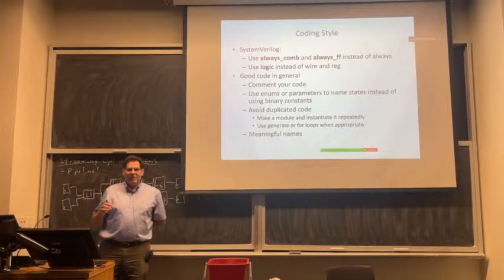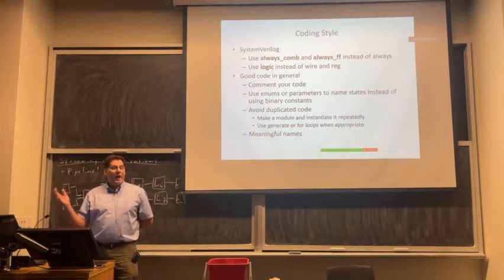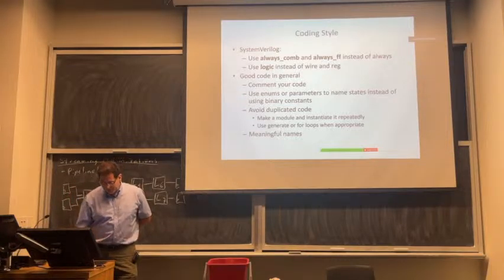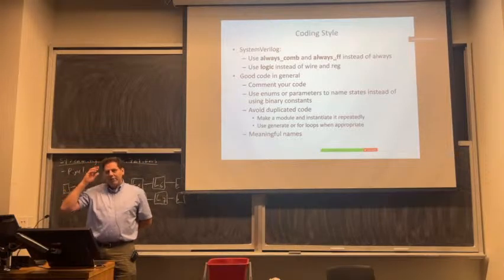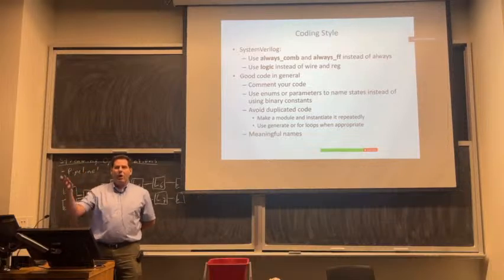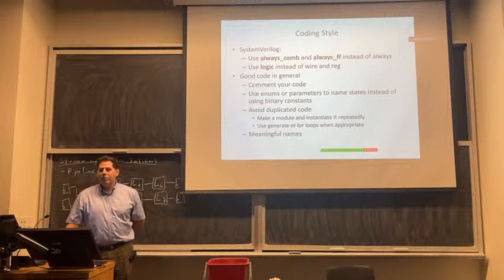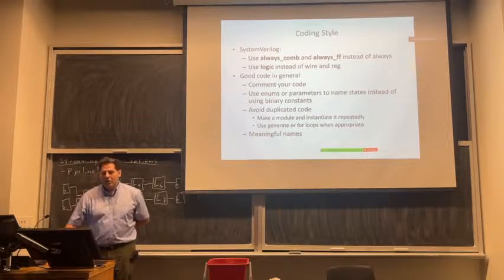So here's a few suggestions of things that you should do in SystemVerilog differently than you used to do. You don't have to, right? It'll still compile if you don't follow this. But basically, because always blocks are basically just processes in a communicating sequential process model, initially in Verilog, when they decided, okay, let's make this synthesizable, you just use an always block, whether it was supposed to be registered logic or combinational. And that actually can lead to a lot of subtle bugs. If you just don't write it quite the way the synthesis tool expects, you'll get something that is not registered logic when you wanted registered logic, not combinational when you wanted combinational.